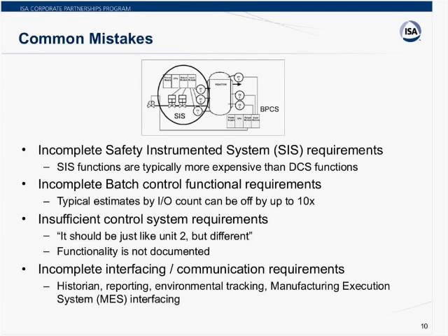I do a lot of work with safety instrumented systems, and when we miss the need for a safety instrumented function, a safety interlock, and we have to go back and add that, those systems are so much more expensive than the basic process control systems. So the safety systems really have a lot more cost. And when we go back and have to move a lot of things or add a lot of things in order to provide additional safety interlocks, that gets really expensive really quick.